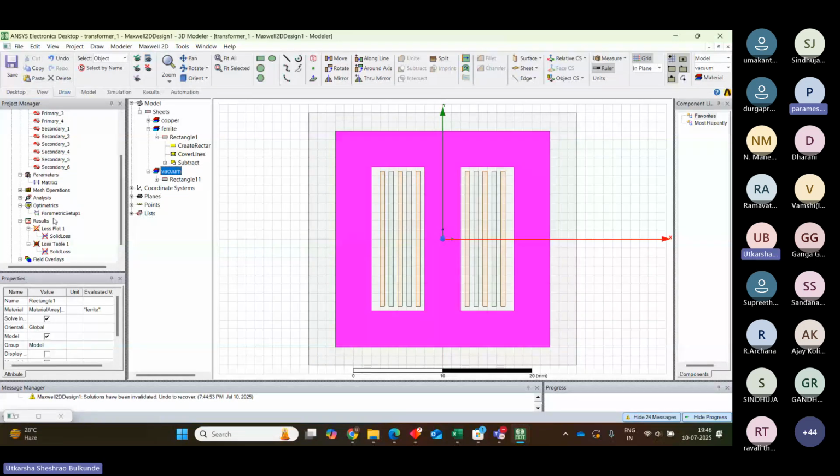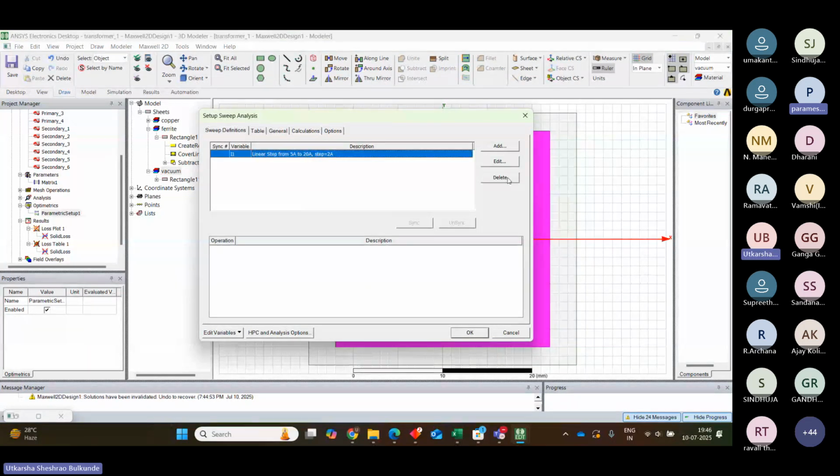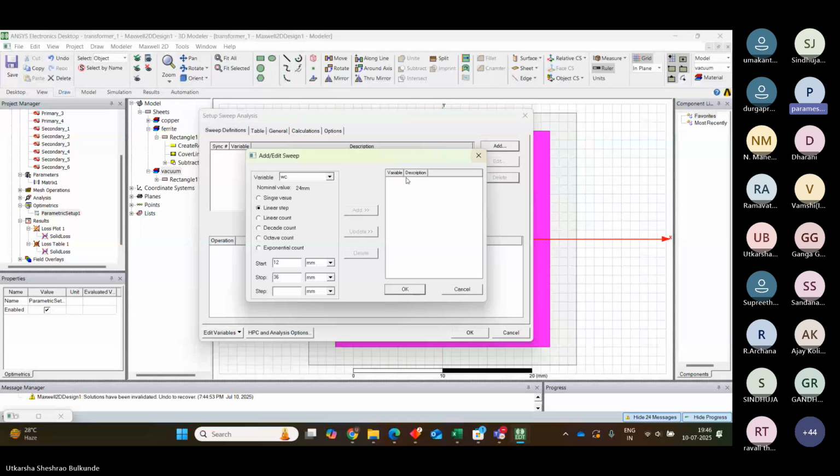Then in Optimetrics, now I'll tell you what to do. We'll just delete this one and add here material index. When we added the grid, it was starting from 0, 1, 2, right? So our start point was 0. Understood now what I'm saying? When I was writing my material at that time, we were forming the grid, serial number wise, 0 was coming first, then second, then third, right?